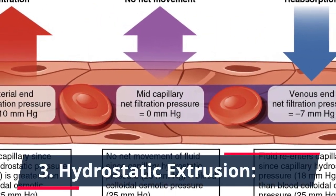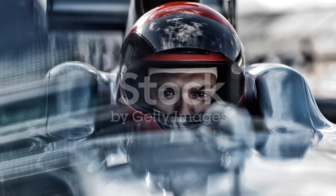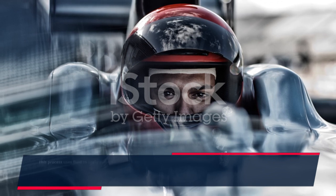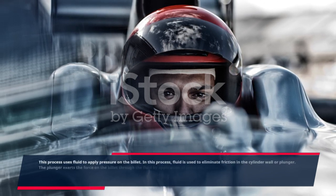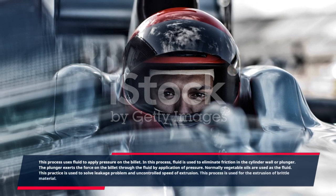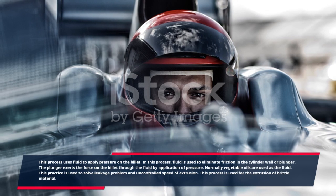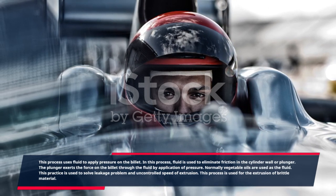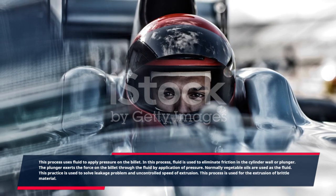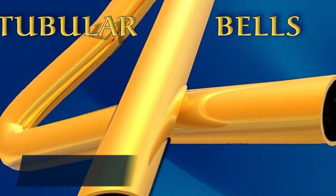3. Hydrostatic extrusion. This process uses fluid to apply pressure on the billet. In this process, fluid is used to eliminate friction at the cylinder wall or plunger. The plunger exerts force on the billet through the fluid by application of pressure. Normally vegetable oils are used as the fluid. This practice is used to solve leakage problems and uncontrolled speed of extrusion. This process is used for the extrusion of brittle material.